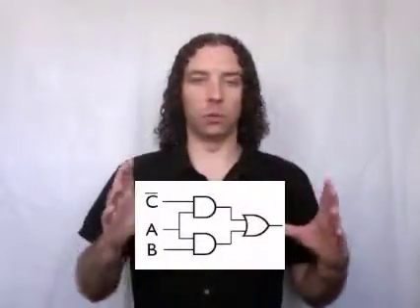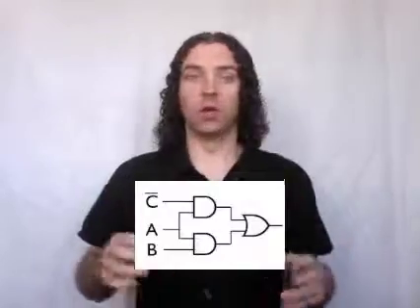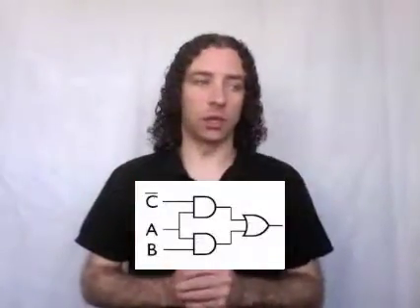It's the idea that a gate itself actually represents essentially a timeable unit of thinking. So from that we can say, okay, in this case we've got 2 gates to get through to get the answer. So this would be a 2-gate delay solution. Now other ways of solving this problem, or other kinds of problems you need to solve, if they have more gates involved in them, a longer furthest path through the whole system to get to the final gate, they'd have a longer gate delay. And so that's what on a CPU would determine what your maximum clock speed can be, is the longest sequence of gates in any one intermediate operation.